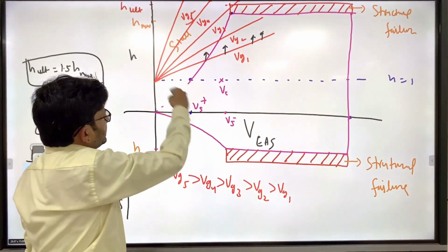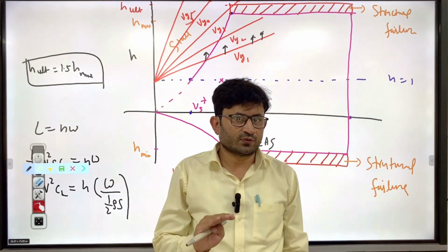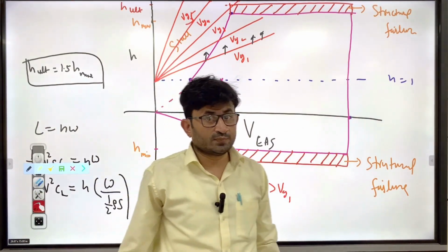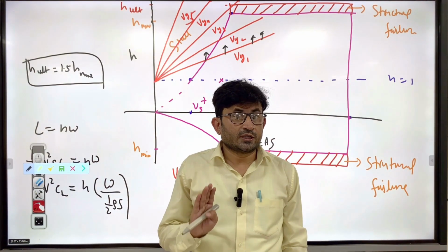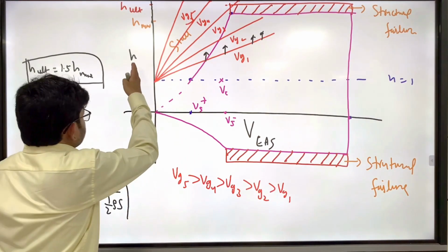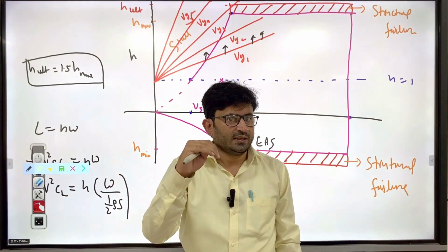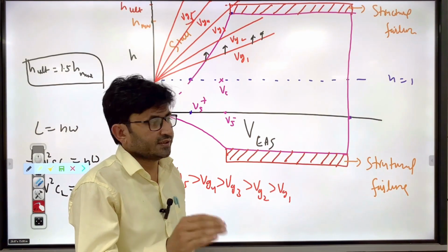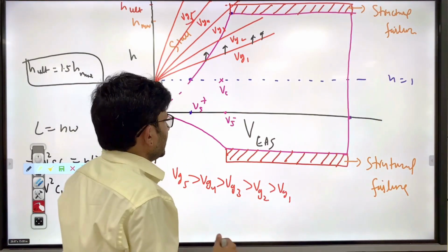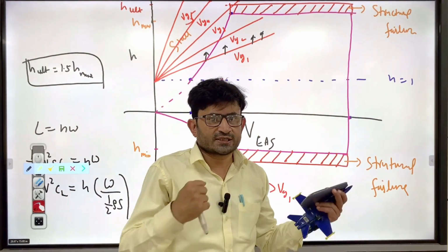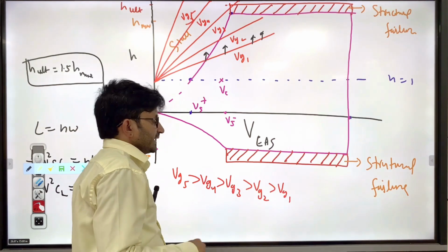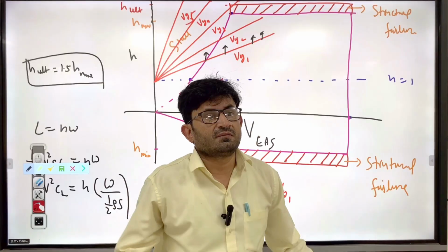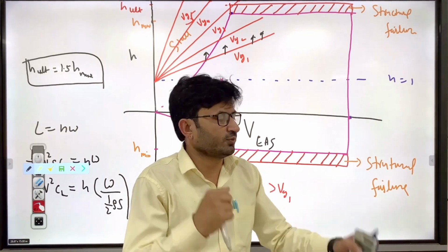Similarly, you can draw the mirror image, and that will be the case for negative load factor. So I hope the thing is clear. Again, I am telling you, in order to draw the VN diagram, take load factor on one axis and decide the maximum load factor. For example, 2, 2.5, 3.8. Like commercial aircraft, I already told you 3.8, and why it can bend to 75 degrees. If you have a stronger structure, more load factor will be there. And again, as an aircraft design engineer, if you design for more structural strength, aircraft weight will drastically increase. So you have to have a compromise.